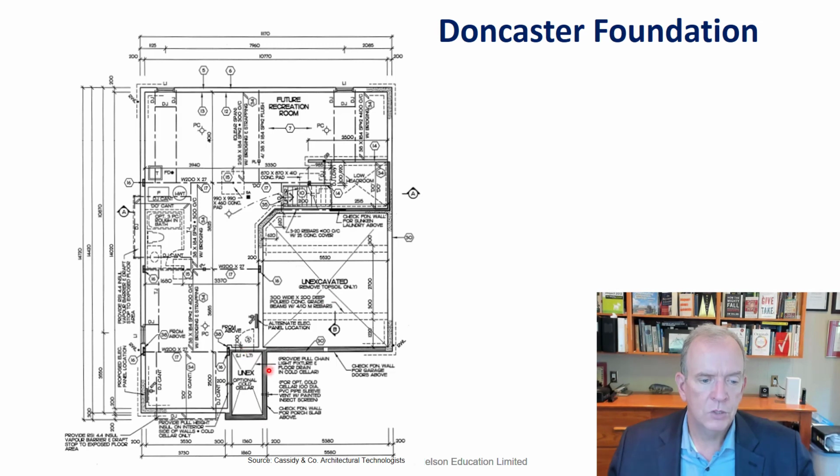That's the foundation. The foundation wall is following this all the way around through here. This is where that cutout is that we were looking at for the sunken laundry area as you enter through the garage, because the next floor plan would show you entering through the garage. And this is where your floor joists are going to be placed for the first floor. The size of the floor joists are always shown in the actual foundation plan. So the technology of building our typical foundation is going to use concrete footings, concrete foundation walls to support the wood frame construction above it.